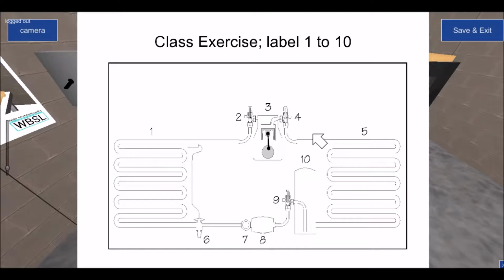that's the typical conditions. So in other words, that you understand this here, and the reason why a lot of these diagrams show the metering device in the middle and so on, you can literally split this down and say over here to the top right hand side is high pressure, high temperature vapor, bottom right hand side high pressure, high temperature subcooled liquid, lower left hand side low pressure, low temperature liquid, top left hand side of my screen low pressure, low temperature superheated vapor.